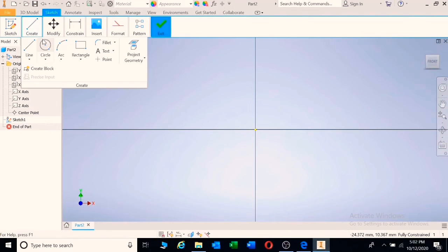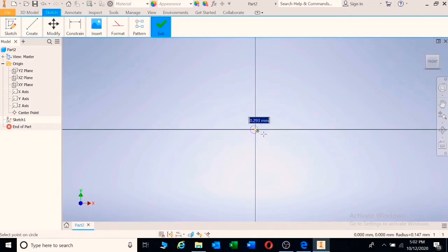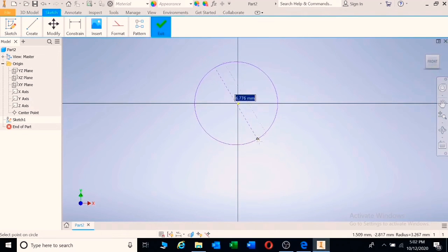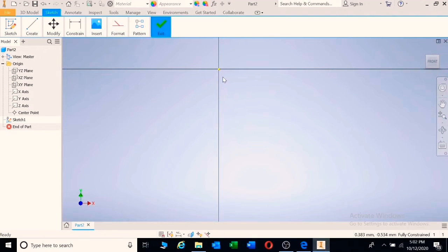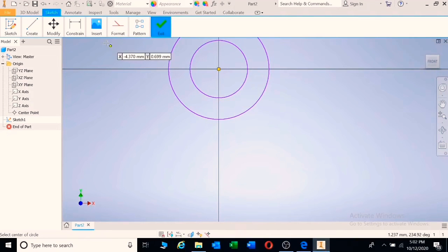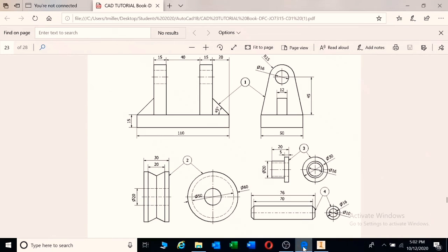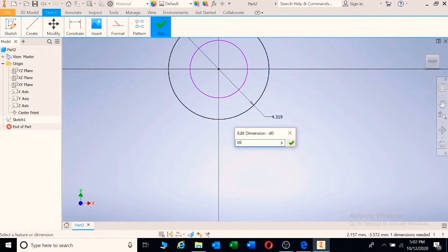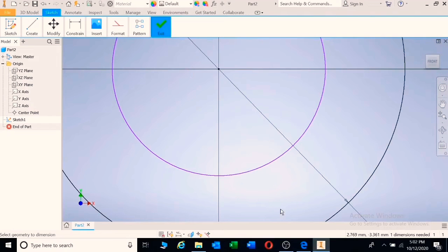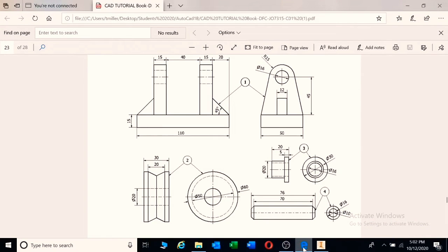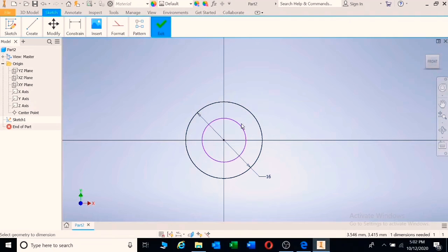We've already started our sketch. We've got a circle here. Let's make sure it's in the center. If it's not in the center, escape and press enter to go back in your circle function. 1 and 2, our dimensions here. Let's check quickly. My memory is not that great, so we have 16 and enter. Next one we have 30, 30 and enter.